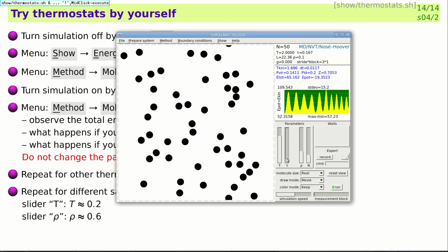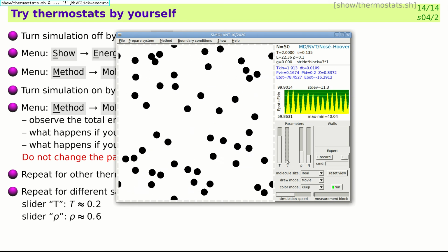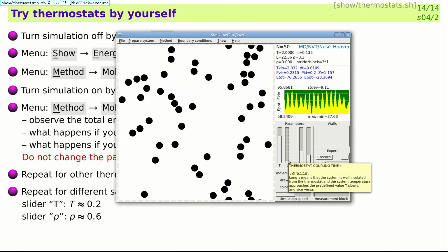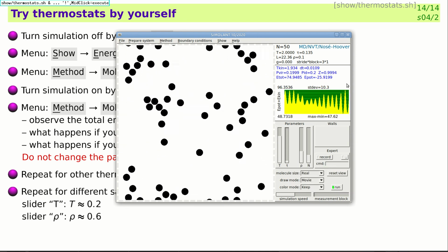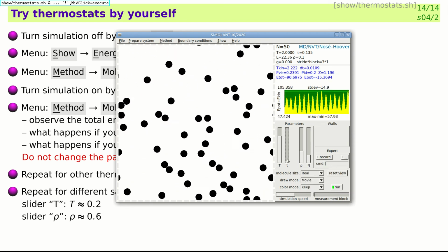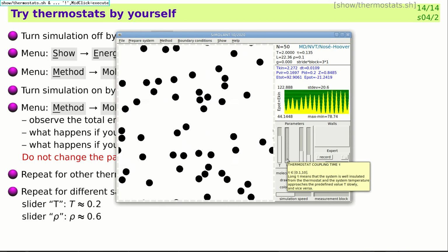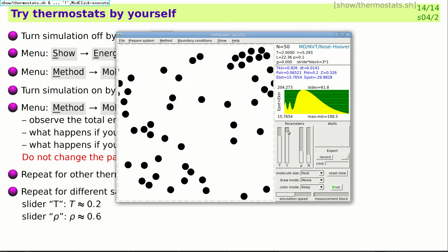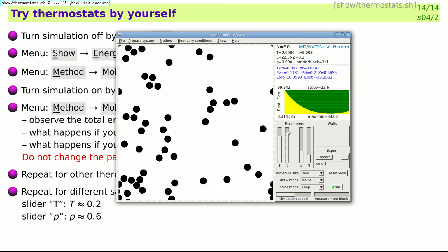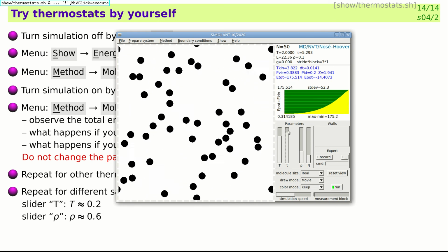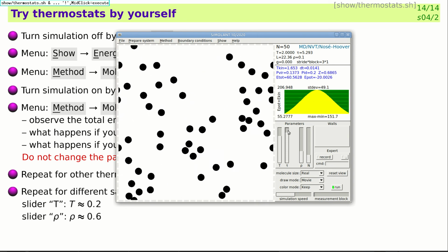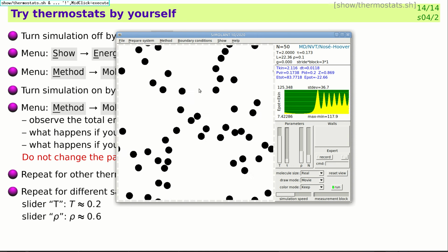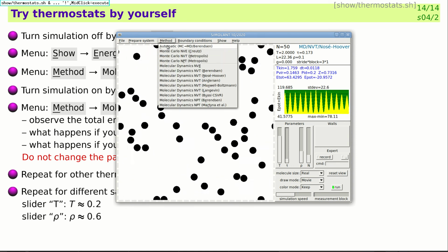So here, if I shorten the correlation time of the thermostat, not the time step, it is the default one. This is quite shorter and would be a better thermostat now. And here it would be very, very long, so I wouldn't recommend this. It apparently causes artifacts, so this is not good. Let's return back here.